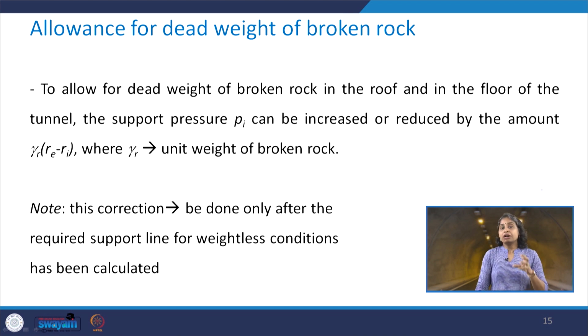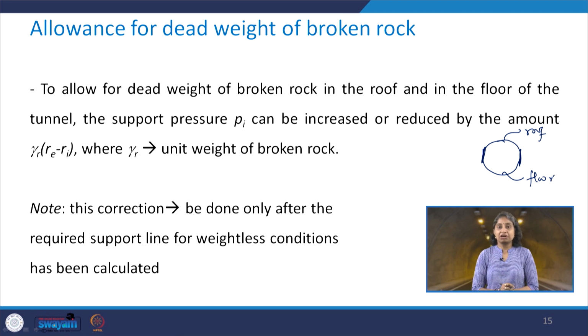In order to allow for the dead weight of the broken rock in the roof and the floor of the tunnel, you see that if this is the tunnel, this portion will be considered as the side walls, this is the roof portion and this is the floor portion, or we call it the invert as well.